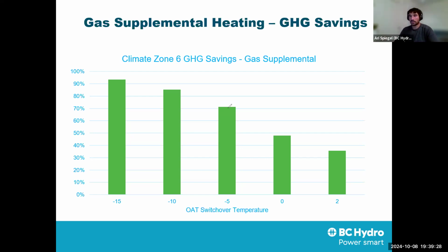And then in terms of sizing, the typical approach that I would see in areas outside Lower Mainland is a lot of people size their heat pump for cooling, because that's kind of the driver. They say, I previously didn't have cooling, I want cooling, I might as well put in a heat pump, because then I get the benefit of both emission reduction, lower cost heating, and the cooling.